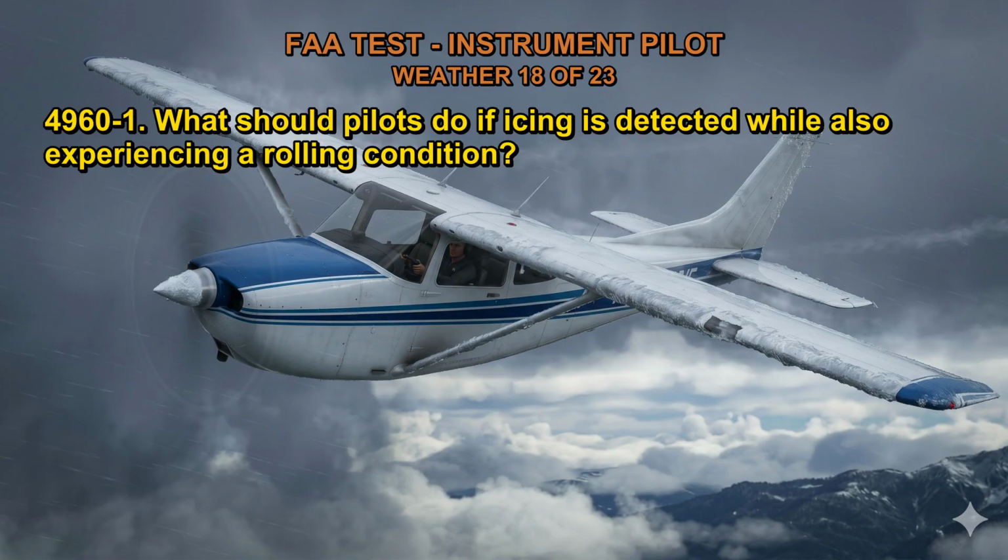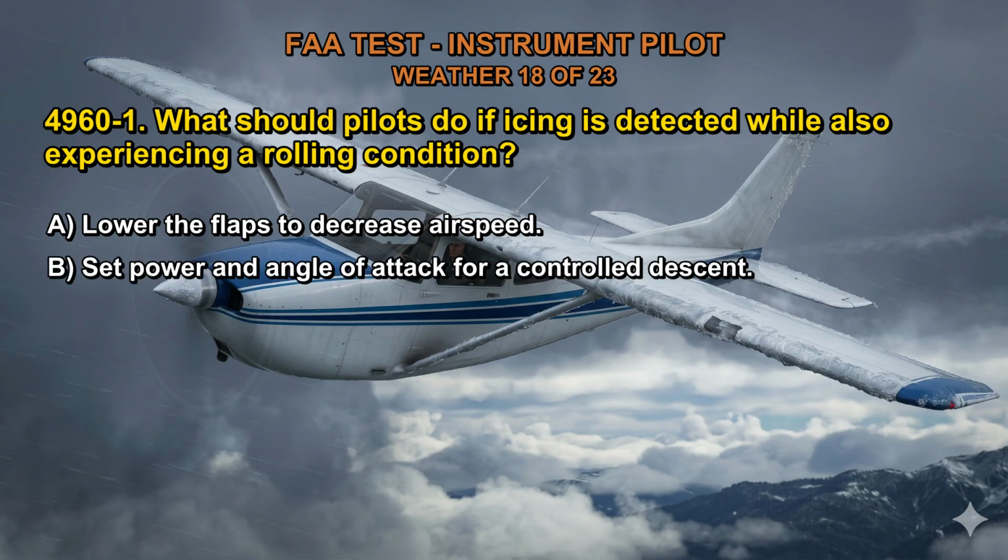For Q4960-1, what should pilots do if icing is detected while also experiencing a rolling condition? A. Lower the flaps to decrease airspeed. B. Set power and angle of attack for a controlled descent. C. Retract flaps and increase power.